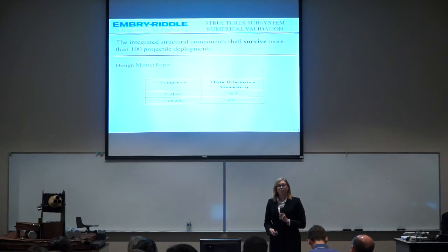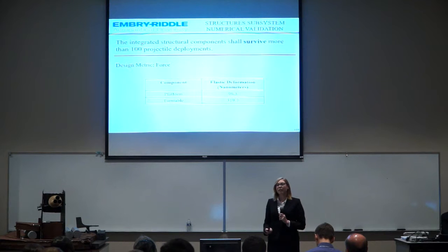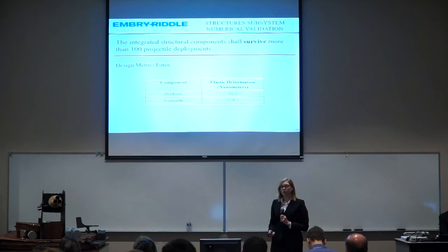Next, we looked at the deformation in the platform and turntable. Under the same force, the platform will deform 96.5 nanometers and the turntable will deform 319.7 nanometers. These deformations will not impede the functionality of our structure.